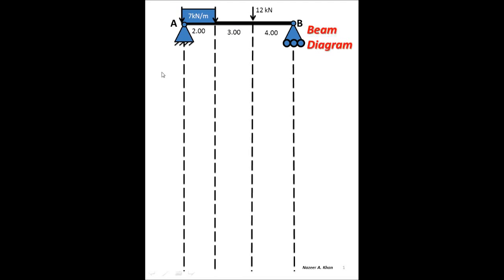These guidelines are here because we're going to place a stack of diagrams. First one that's going to happen is a free body diagram, and if we didn't have, again, the simple beam here, we couldn't construct a free body diagram. So the next diagram is dependent on the previous diagram, and after the free body diagram we're going to do a deflected shape, and we're going to do a little bit of an explanation there. We're going to do a load diagram, shear force diagram, and then finally a bending moment diagram. And the shear force diagram, the maximum deviation, we're going to pick that number of, and same with the bending moment diagram. So let's go and create our FBD.